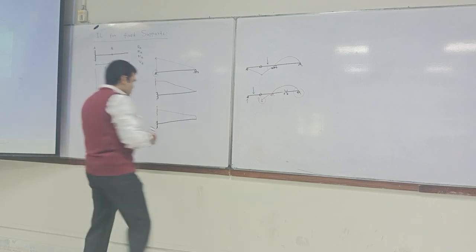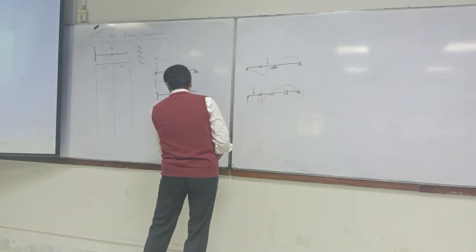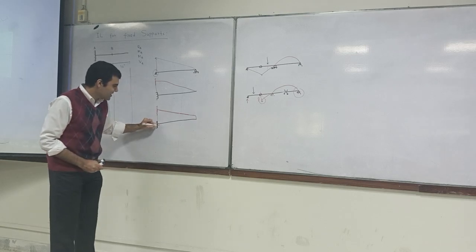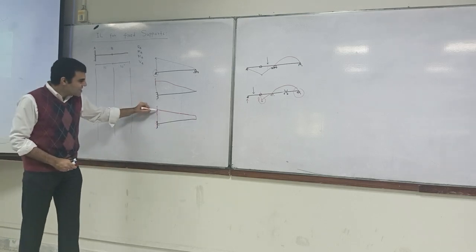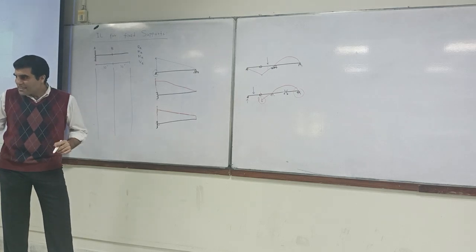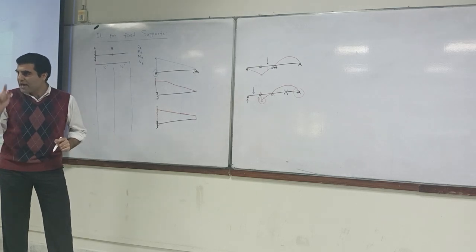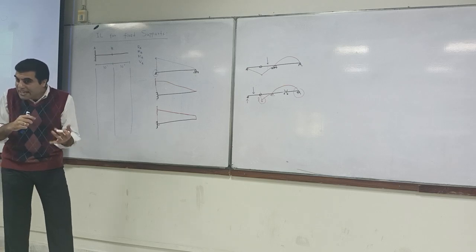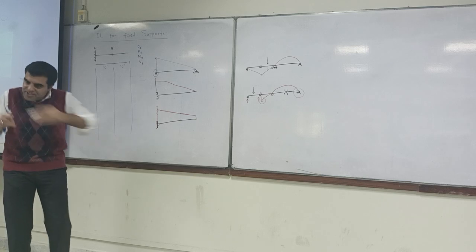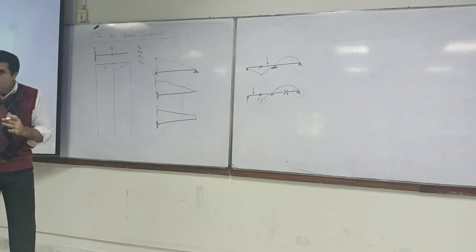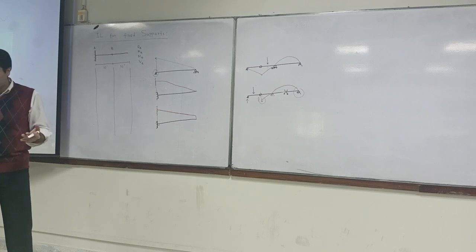Look, this one is telling you that initially it was 90 degrees. Now this inclination has changed, it has reduced. But I told you that according to Muller-Breslau principle, you are not going to change the kinematics, everything related to the elastic curve, to the deformed profile. So the deformed profile, you shouldn't change.